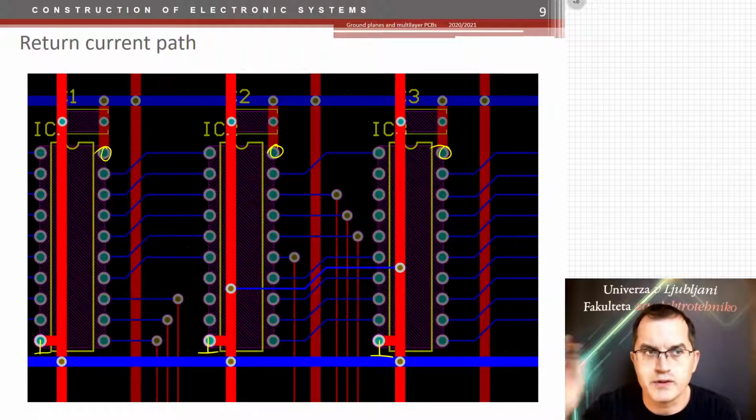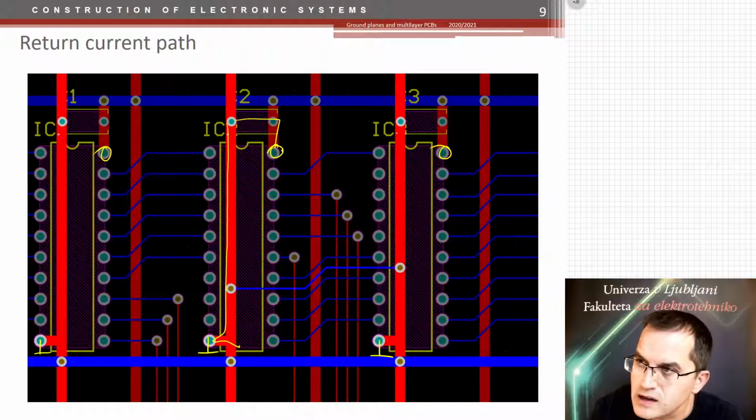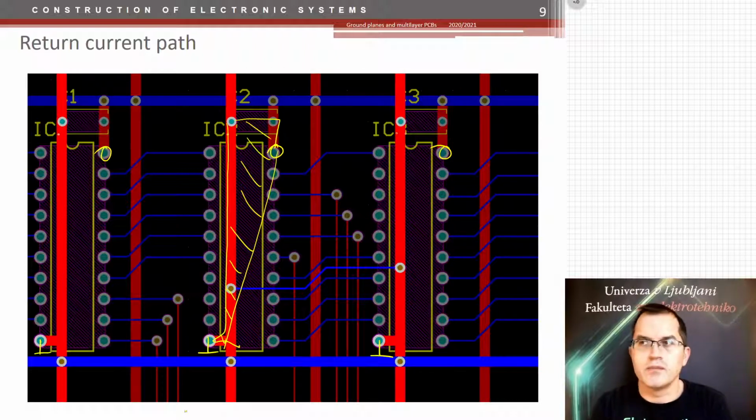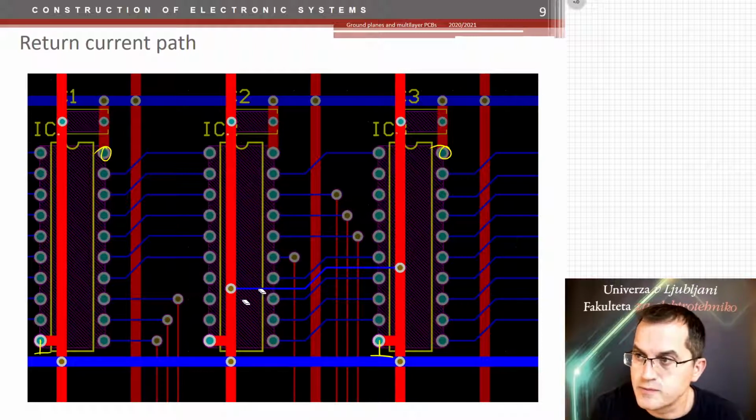Power supply on top right, ground on bottom left. And these were then able to connect very, very regularly. But this also caused a lot of problems with bypassing, because now the simple area of that bypassing circuit itself, not accounting for all the rest, is already quite large. And by that, you cannot bypass high frequency currents. So these circuits never were able to work at high frequencies, more than a few megahertz, like these first computers were actually made to work at.